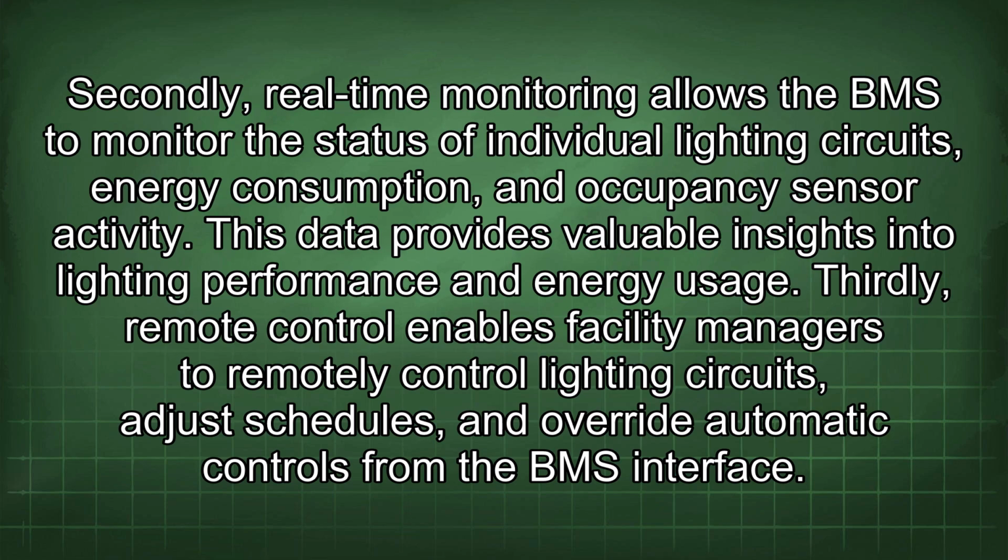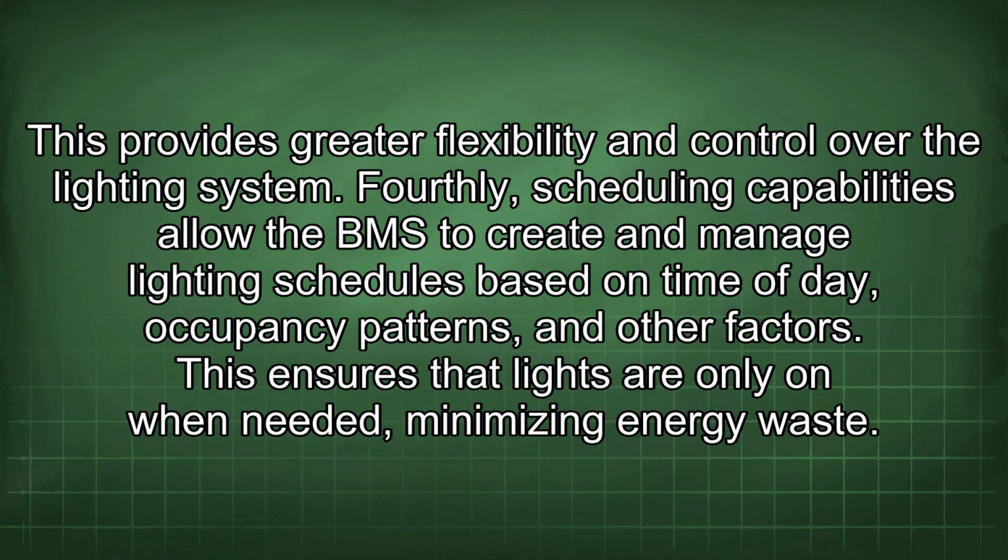Thirdly, remote control enables facility managers to remotely control lighting circuits, adjust schedules, and override automatic controls from the BMS interface. This provides greater flexibility and control over the lighting system. Fourthly, scheduling capabilities allow the BMS to create and manage lighting schedules based on time of day, occupancy patterns, and other factors.